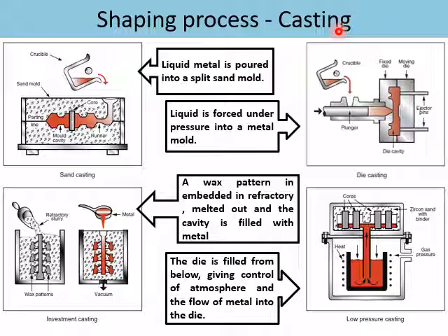Low pressure casting combines the mold with the furnace over here. From the furnace, metallic material is liquefied and pushed upwards towards the die using gas pressure, usually inert gas such as nitrogen. The metal liquid fills the cavity, which could be made from zircon sand and also binder.